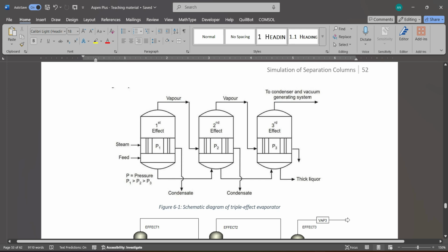Whereas the salt solution keeps gaining concentration from each stage as an effect of the evaporation of water vapors from the brine solution. Ultimately, a thick liquor can be obtained from the last stage of the multi-effect evaporator. And from each stage, the vapors being used for heating purposes are considered to fully condense and provide the latent heat for the evaporation.